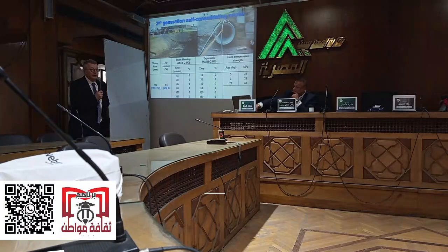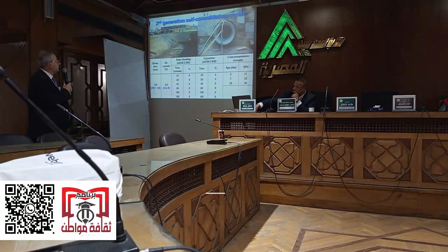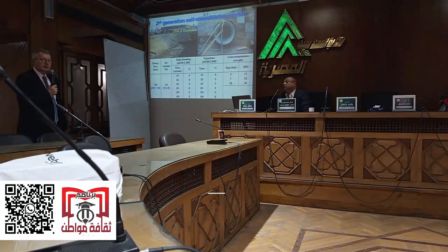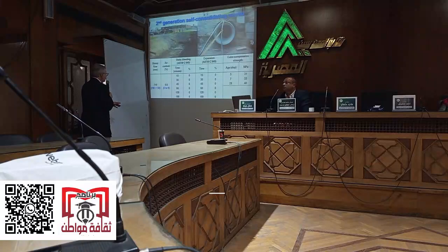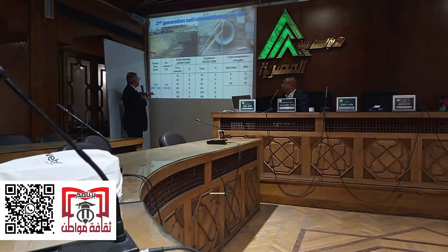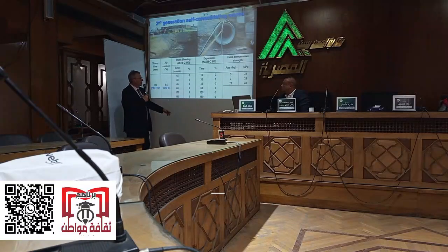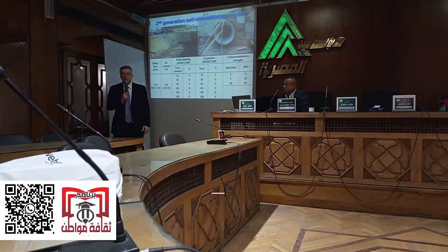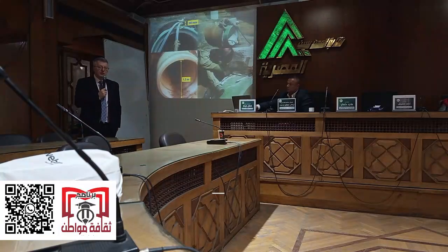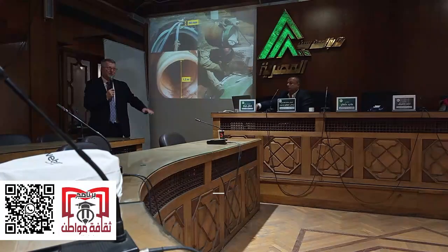So finally, we decided to do a study on one of the materials, and it was a self-consolidated mortar that was mixed in a ready-mixed concrete truck. So sand and water, you could see the properties. The slump flow was 710, the air content, static bleeding 0, expansion, compressive strengths, adequate. Of course, the most important test is the penetration.